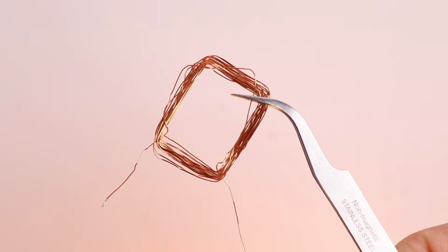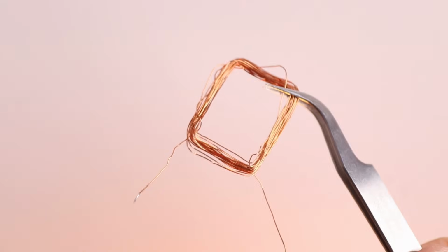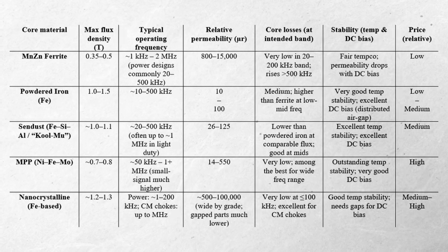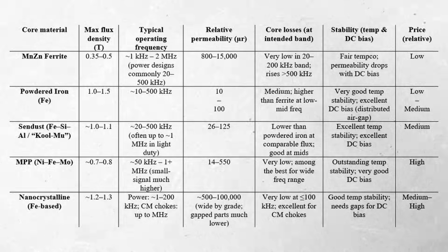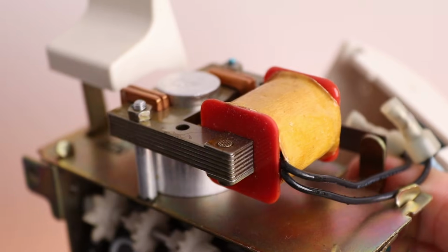But obviously nothing in electronics comes without trade-offs. Magnetic materials cost money. They also increase losses, especially at high frequencies. And the most important issue, saturation. On the other hand, when no core is used, what's called an air core inductor, there is no saturation problem and no core losses. So to sum up, there are different core materials with different properties. Only some of them are listed in the table here. But I just want to show you a simple experiment with only 2 materials.